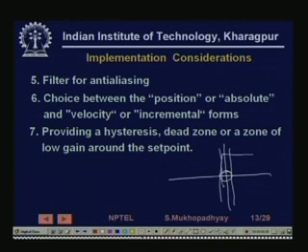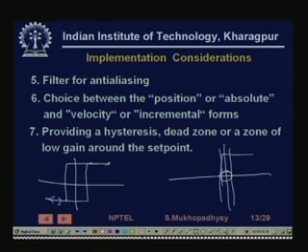So, you put a hysteresis, let me draw it clearly. You have an input output characteristic and you have a hysteresis curve. If the error is in this zone, then I am going to basically maintain. If I was here, I will maintain unless the error goes out of this zone. So, this is a hysteresis switch, right.